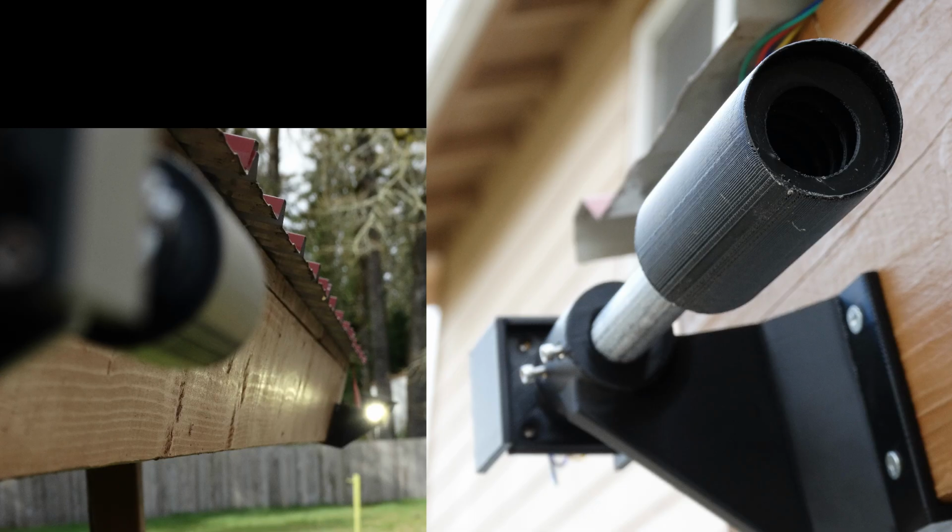I've been testing this over the last year with the TCS34725 sensor, and I just got the OPT4048 sensor working on it, and I'm looking at the results right now to determine whether or not this is working and useful. I'll probably have to use some digital filtering on it. However, it's transmitting light, receiving light, and we'll let it go through a few daylight cycles to figure out if we can take the background noise out of it.